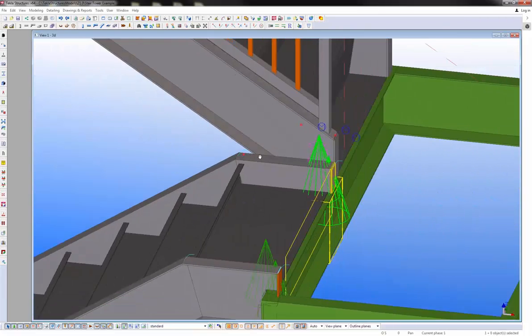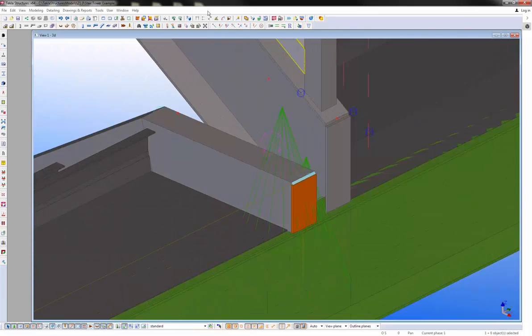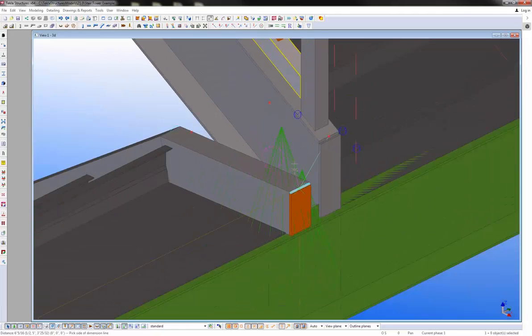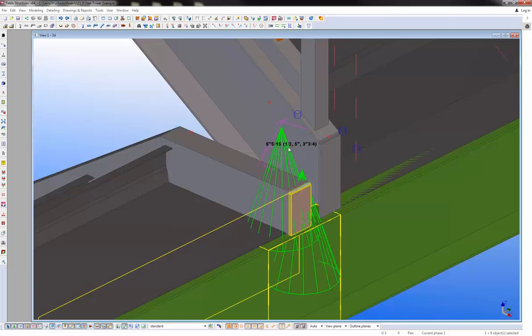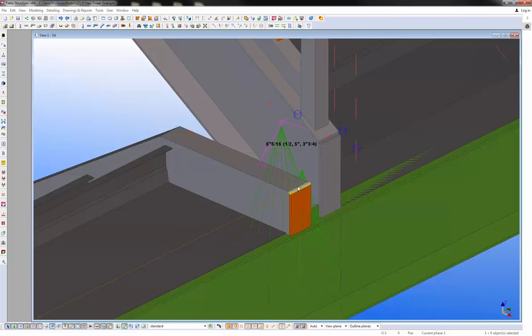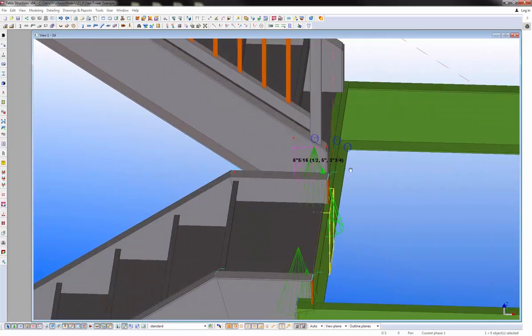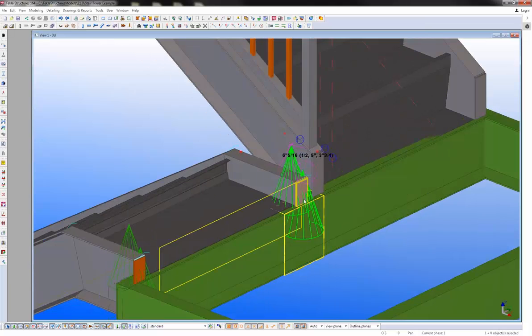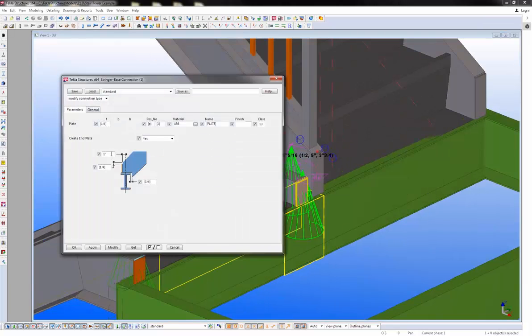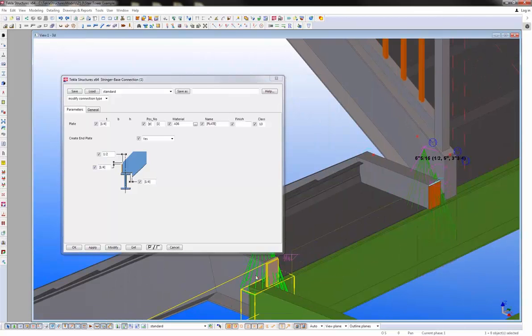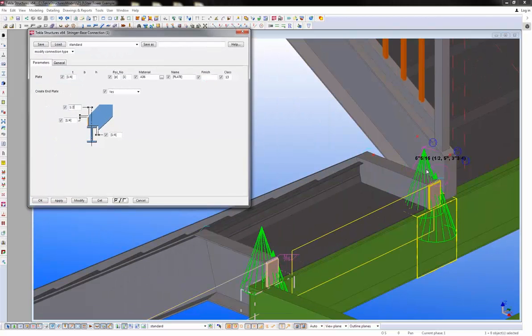So let me measure. I want to make sure that my stair ends match here. Right now I'm looking at a 1/2 inch difference in the X between the end of the lower stringer and the end of the upper stringer. It looks like it's a 1/2 inch beyond, so I'll pull back that component. Instead of saying it's an inch past center line, I'll make it a 1/2 inch past center line. Make sure I adjust both of those components.